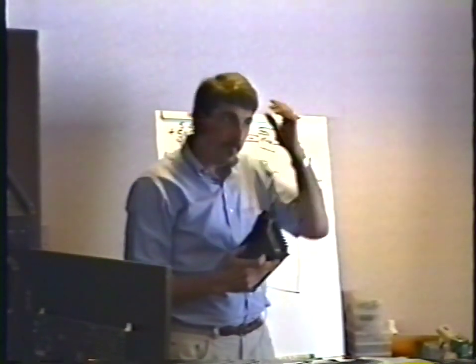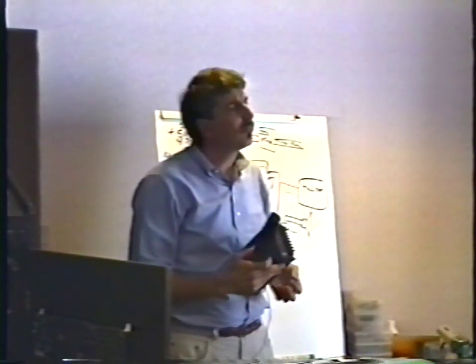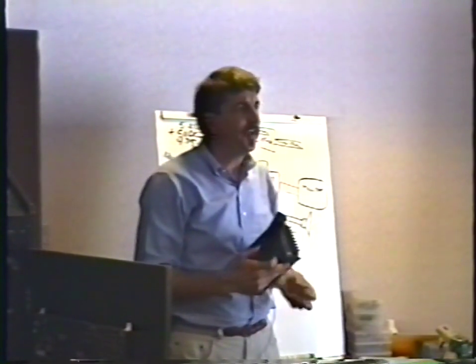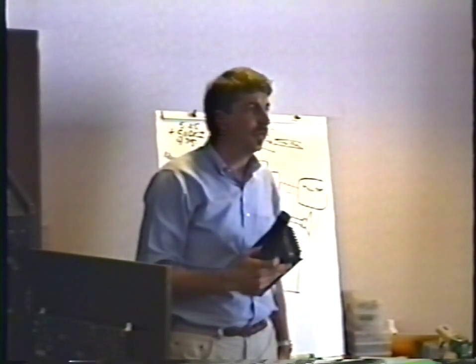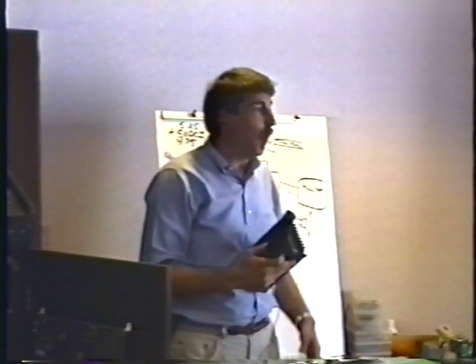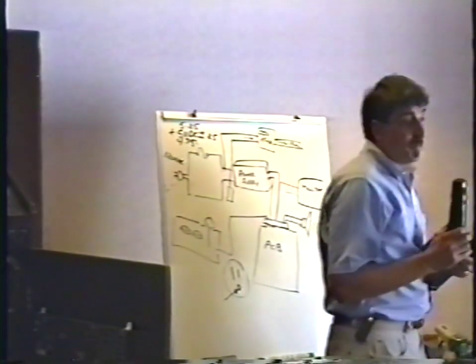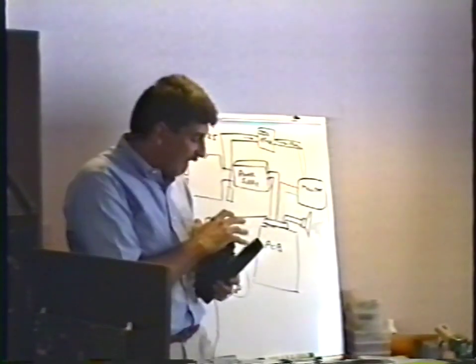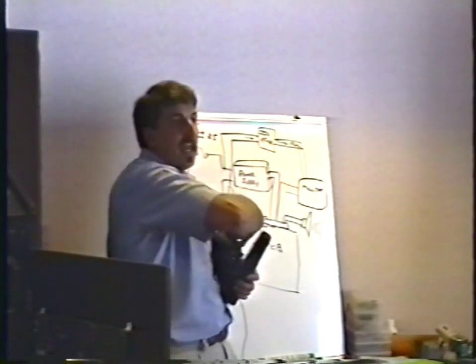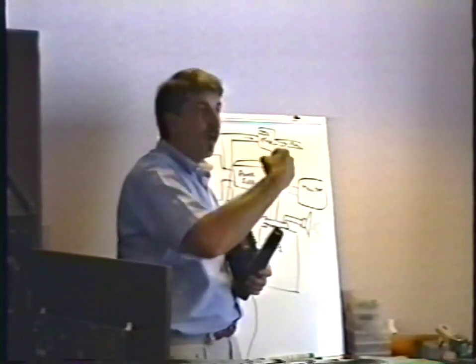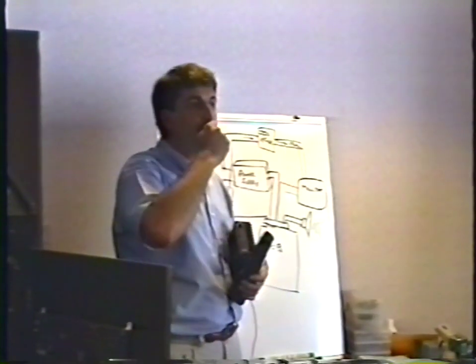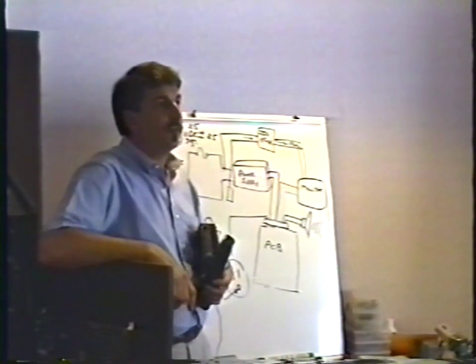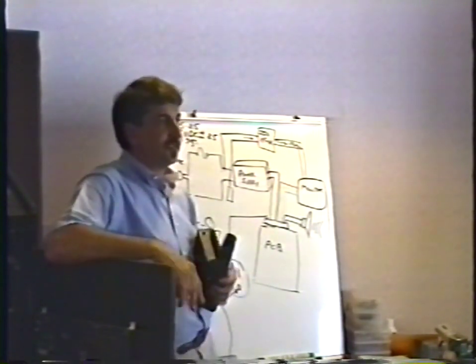So it might be good to unplug it and do it, plug it in and see what you got. You can't adjust it when it's unplugged. I mean, I could unplug it off the board and do it and then put it on. No, because that comes back to what Howard was mentioning earlier, and I'll amplify this tomorrow. In order to adequately test the power supply, it must have a load on it. You must be sucking current out of it. Again, after I stick it back on and see how it is. No, don't do that. Leave it all connected. Just adjust it with the power turned on.